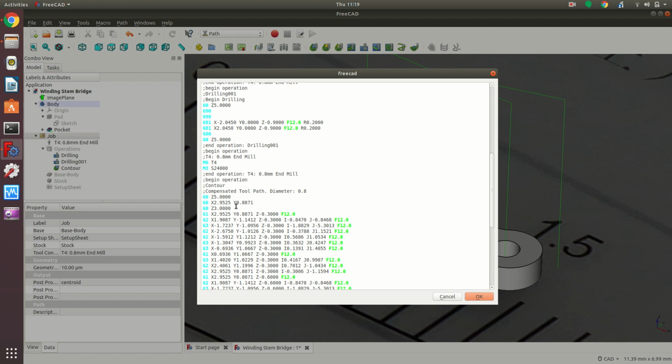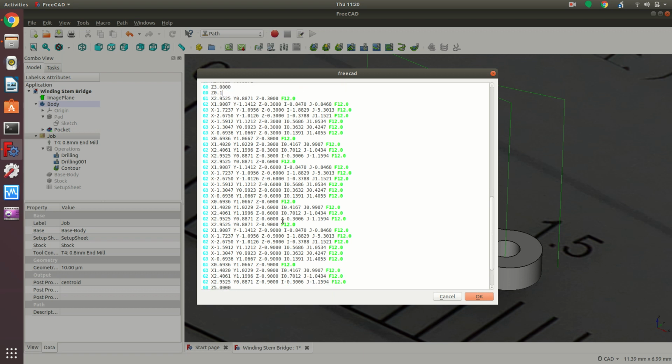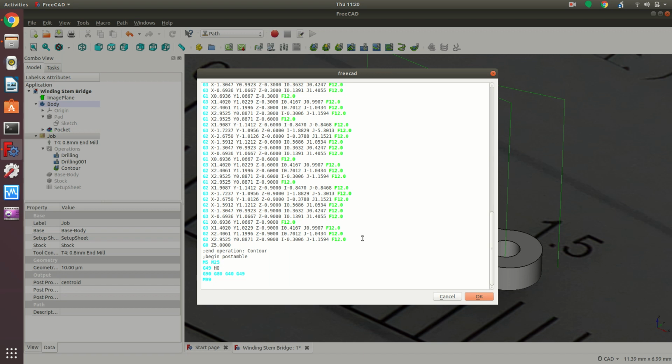And then we have the toolpath for the contour. What we do here, it says it goes to Z3, and then it would slowly descend, and we'd be standing here for 2 minutes. We just say G0, Z 0.1, meaning it goes to a tenth above the workpiece, and then it descends to minus 0.3, and then it starts working on the contour. That just speeds things up. And then we just sanity check, 0.3, 0.6, 0.9, speed 12, so F12, that's okay for brass. In stainless steel, that would ring alarm bells. Without cooling, you couldn't do that. Okay, we're done.